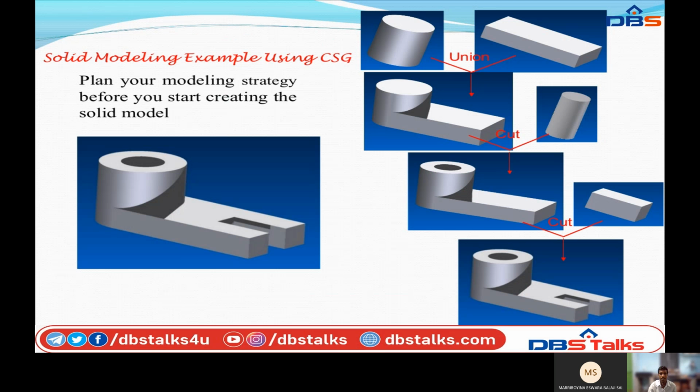Next, solid modeling examples using CSG. Plan your modeling strategy before you start creating a solid model. Here I am taking a solid model, which is generated by following Boolean operations like union, subtraction, and intersection. First, for preparing this type of solid model, I take a cut section of a cylinder and one rectangular plate, two different primitives.